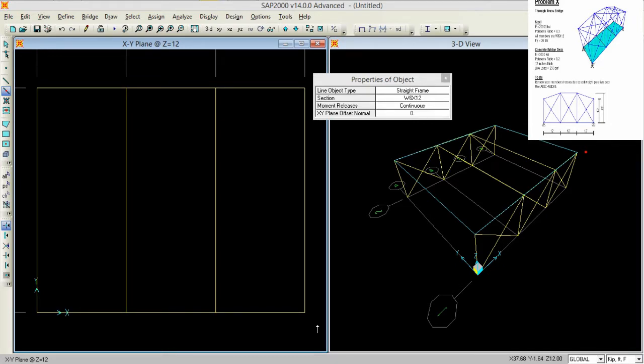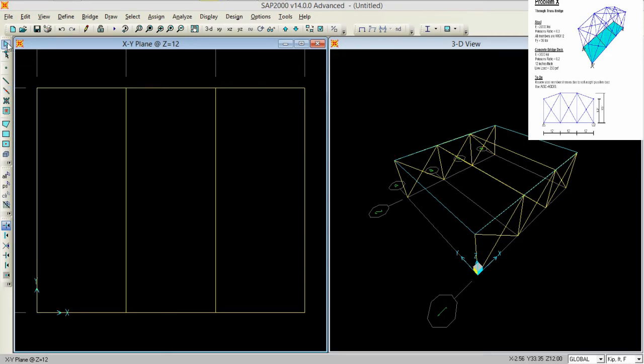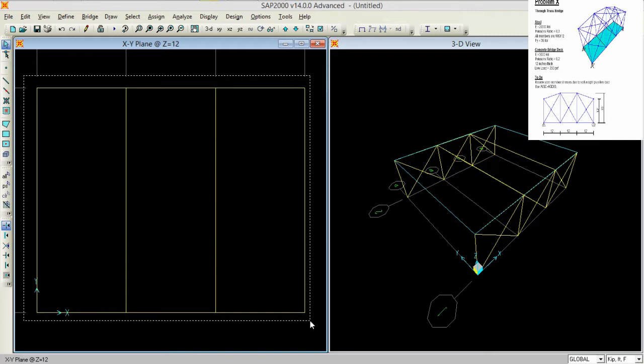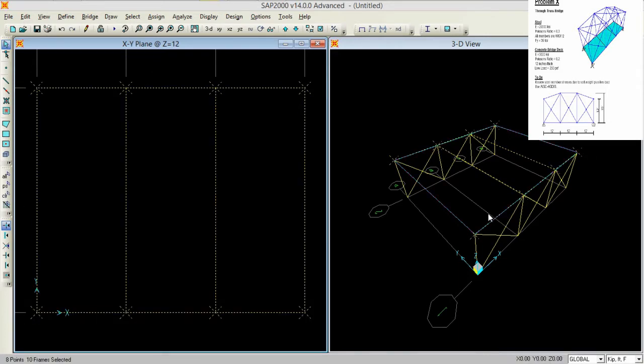The next thing is, now I can add braces over here, but first let me do something else. Just going to this, selecting this as a whole. So look, if I am adding braces over here, I have to replicate it down as well, under the deck. We do not need braces under the deck. If we need, then we can draw braces and then replicate them down. But as we do not need any braces, we will go without braces on this.